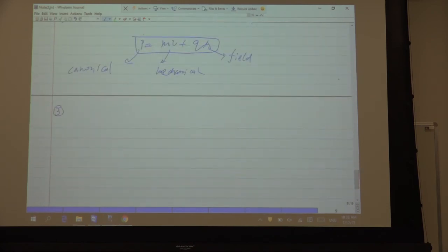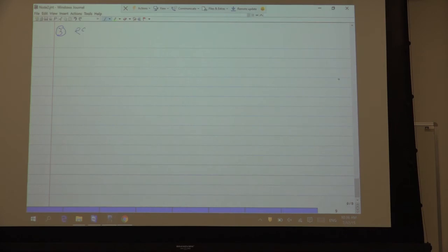Now the third law is very important, called the equivalent principle. Say there is a source J, and I want to know the EM field outside this circle. I want to know the E field and H field outside. How do we calculate them? First, you can use the Green function. If you know it's a Hertzian dipole in here, you know the Green function, E(r) equals minus j omega mu times the dyadic Green function G(r, r'), times J(r').